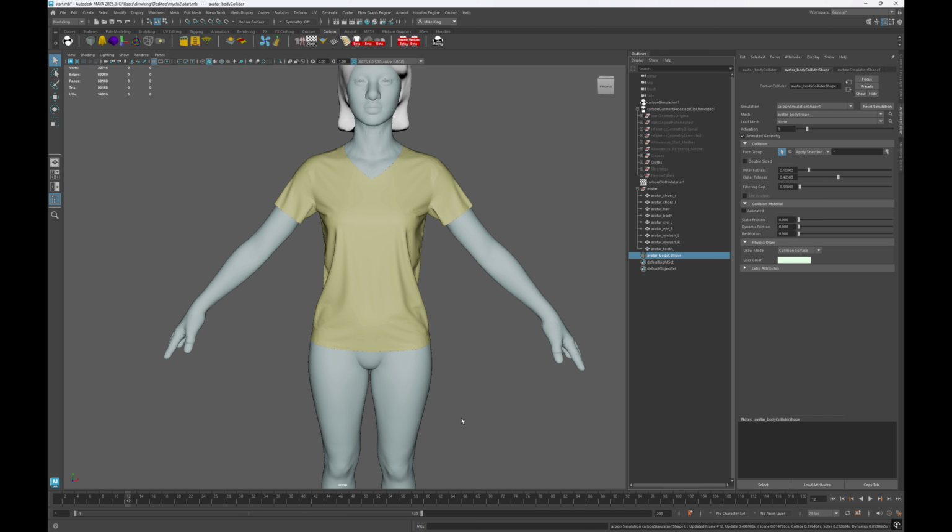But if you want an even more exact result, then you actually need to turn off friction on the avatar in carbon, because the start mesh for the unfitted version of the simulation from CLO is slightly longer. That is impacted by the friction on the body. So here we have an example where I've removed friction from the actual avatar.